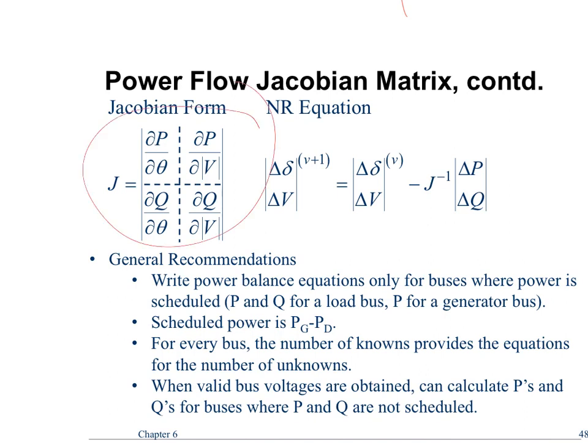Looking at that Jacobian, you can see the partial of P with respect to theta is essentially telling you how sensitive power flows are as you change theta. So if you're an operator at ISO and you're trying to increase real power flow through a line, you can look at the sensitivity matrix and say, well, there's a partial of P with respect to theta, let's say 17.